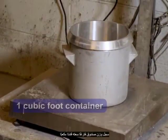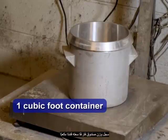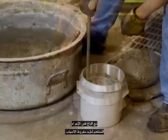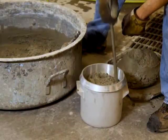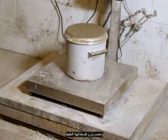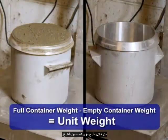Record the weight of an empty 1 cubic foot container, and then fill the container with concrete following the same procedure used to fill the slump cone. Weigh the full container and calculate the unit weight for this mix by subtracting the empty container weight.